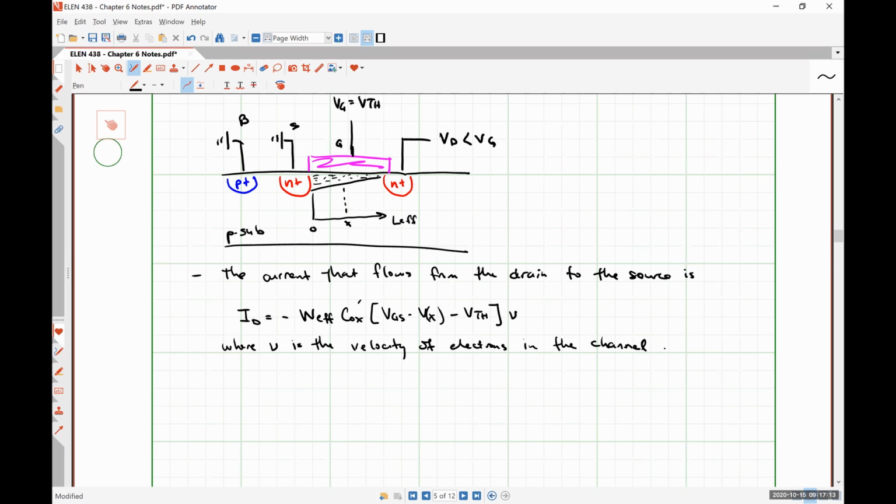All righty. So let me ask you guys, I guess it's an analog electronics 1 question. Is this charge transport from the drain to the source because of drift or diffusion? If there's an E field, I believe that's drift, right? Exactly right. Diffusion is because there's a difference in concentrations. So since our charge movement is due to drift, we can say that